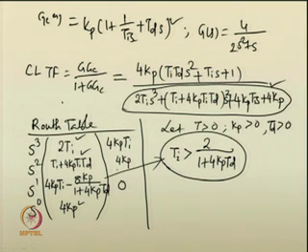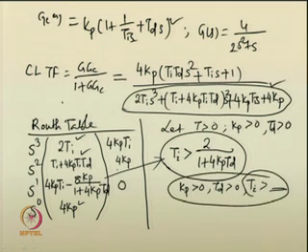It will not blow out. Now, with the choice of Kp greater than 0, Td greater than 0, obviously one can get some constraint on Ti. Ti is greater than some value. If this condition is met, we will certainly get a stable response from the closed loop system.